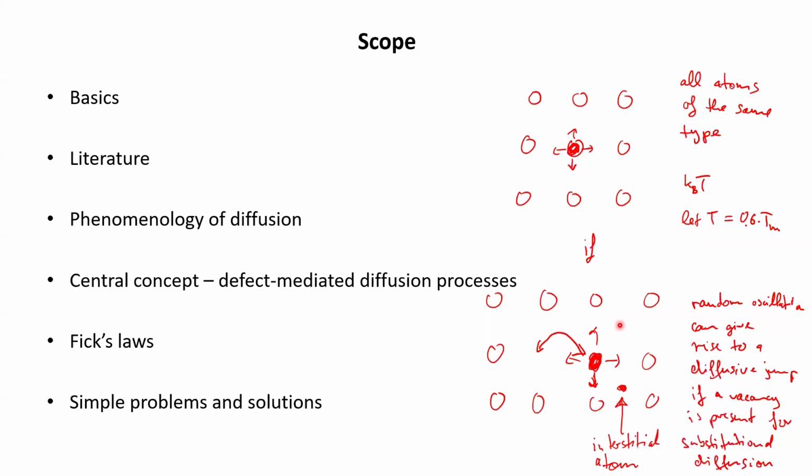This is also what was not done early on in the high entropy alloy work. And this is why the reports on sluggish diffusion came about, by evaluating the wrong type of diffusion measurement and then taking the values in the wrong way to interpret them as self-diffusion coefficients. And so you have to go through this.